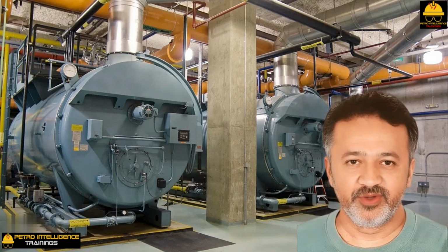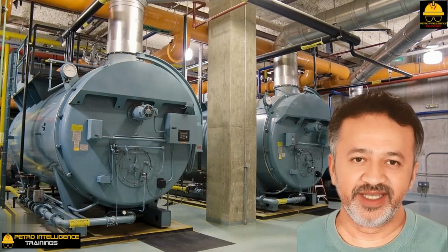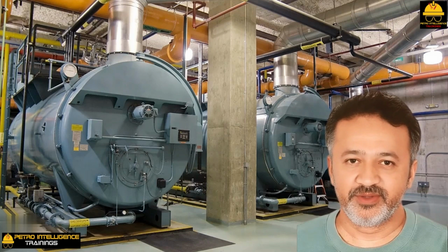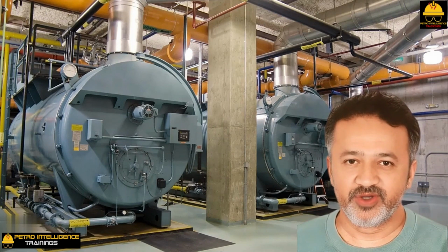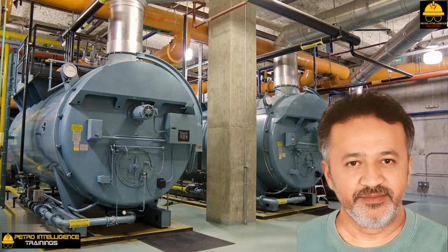On the other hand, 30% condensate recovery as a percentage of the steam generation rate is rather bad and represents sloppy operations and bad condensate recovery design practices. Very approximately, 10% of the cost of steam generation could be saved by recovering the condensate. The condensate contains few silicates, thus no blowdown is needed, no chemical treatment or deaeration is required, and no energy that would otherwise be used to preheat the boiler feedwater will be wasted.